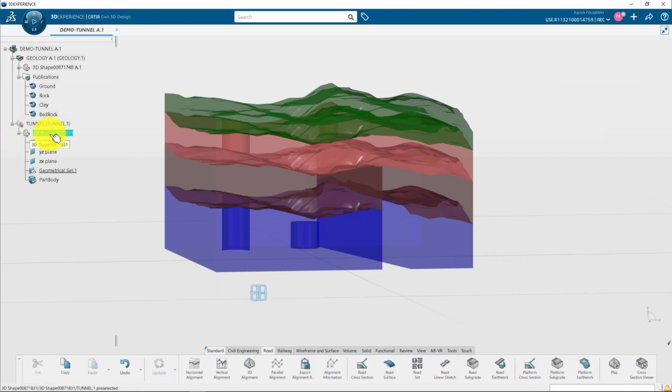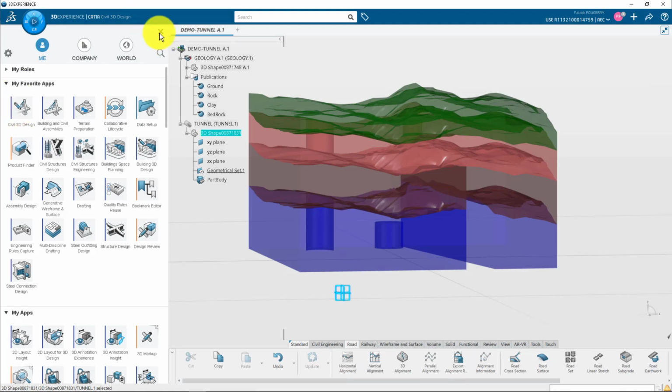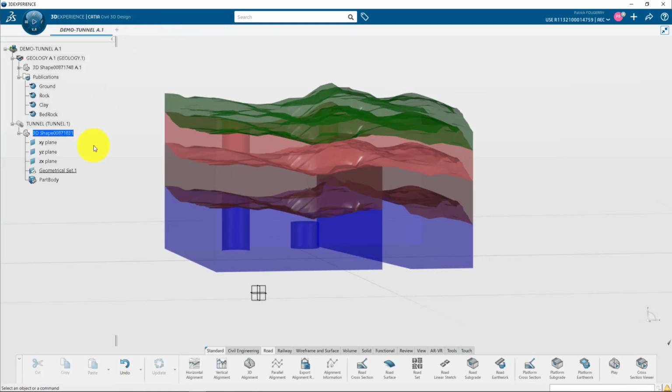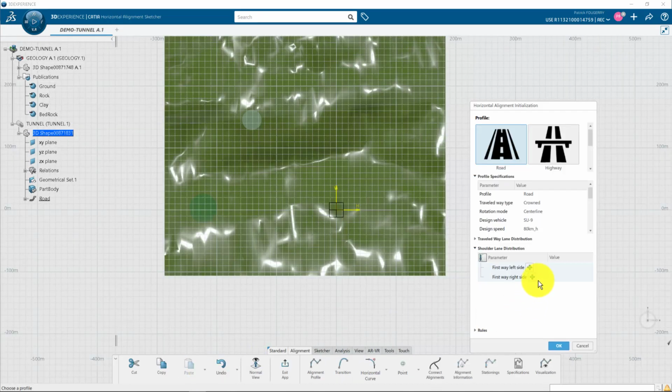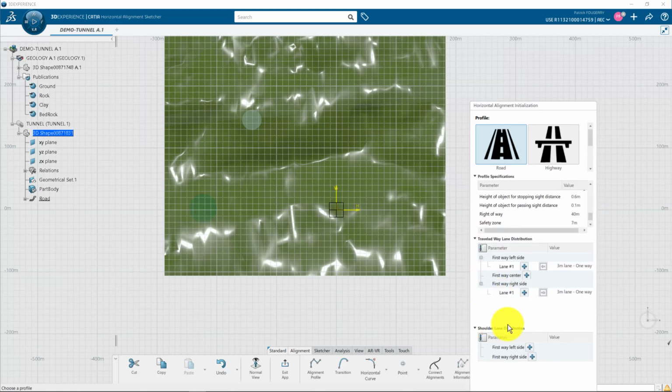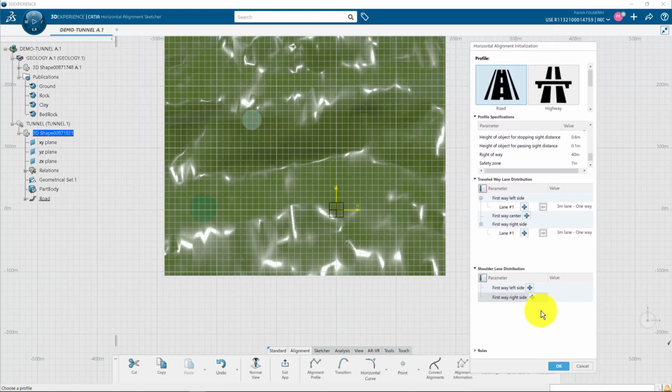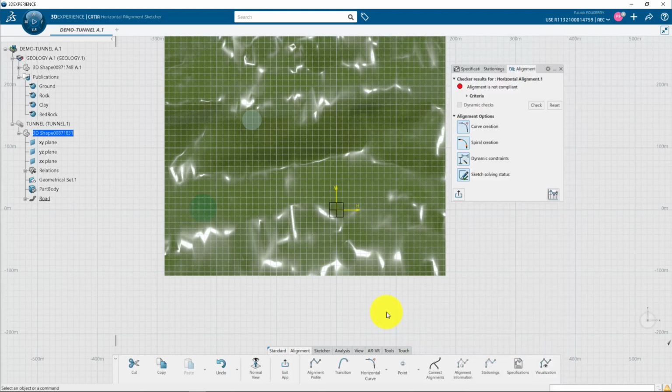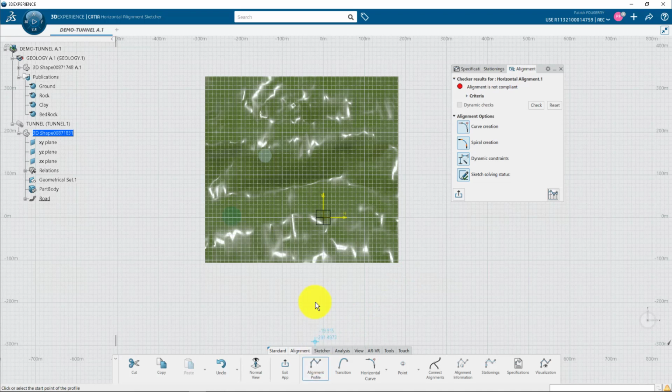I will use the Civil 3D Design application and will first create an alignment. You can either use the road or railway tabs depending on your project. I click on horizontal alignment, check the different parameters of my road, a road with 2 lanes, and validate. For this example, I will do a really simple straight alignment, but it can be of course a lot more complex than that.